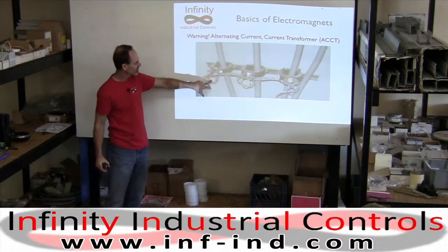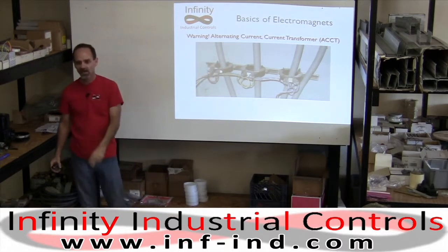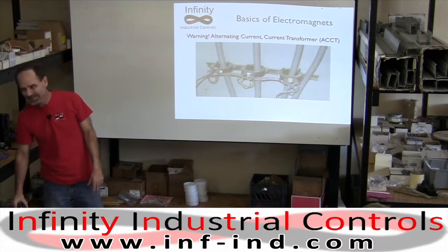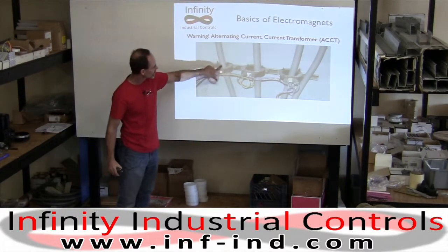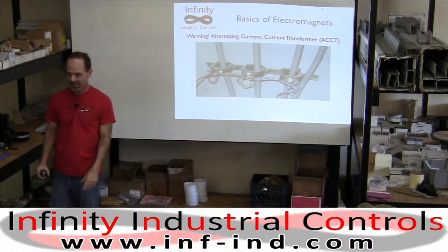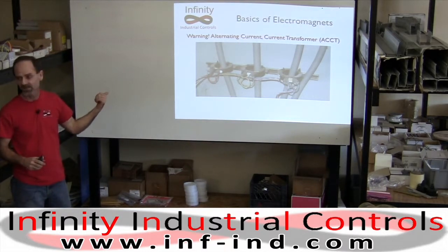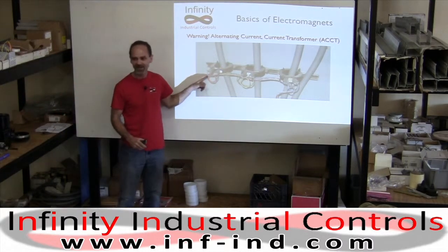But if you leave these terminals open, the pressure in there, the electrical pressure I was talking about, will build up until it can reach the amps that this ratio of turns to this one wire calls for. It'll try to get to the voltage in order to produce the amount of current it needs, and it'll actually break the insulation down, but it can make thousands of volts, and these can kill you very quickly.